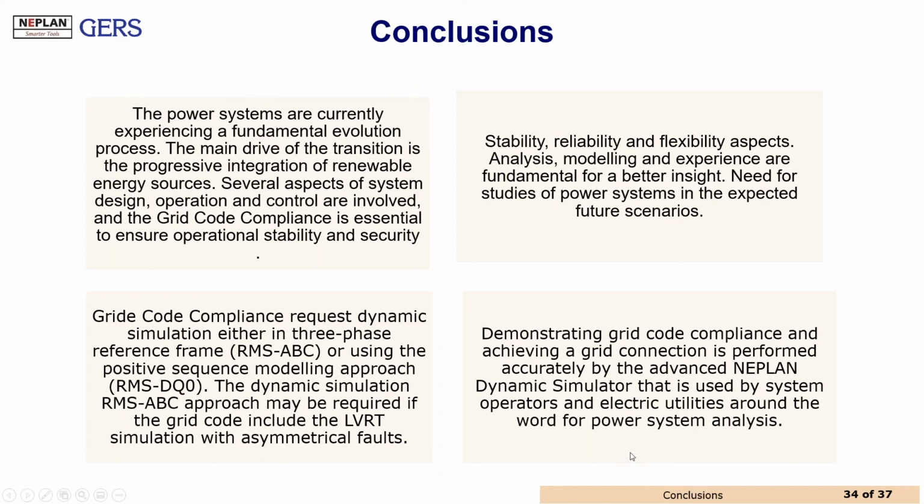Grid code compliance requires dynamic simulations, and as I have been explaining here, the positive sequence modeling approach is useful in symmetrical faults, and the three-phase reference frame is useful for asymmetrical faults, when the grid code requirement is also oriented to low voltage ride-through with asymmetrical faults.